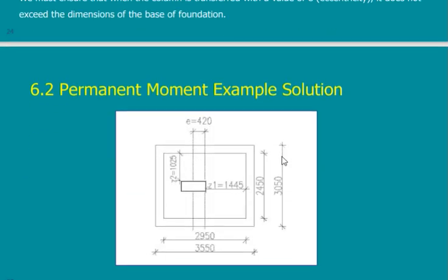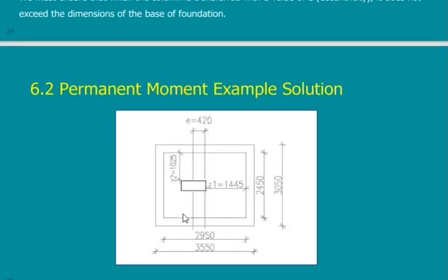This is a sum. So what will happen? These are the dimensions that I've got for L and B, and for plain concrete and reinforced concrete, and I was supposed to have here the CG. Because I have moment in this direction, the moment is coming from this direction to this direction. So if I put the column in the opposite direction, it will induce an opposite moment. I just shift 0.42 meter, and this is my new CG for the moment.